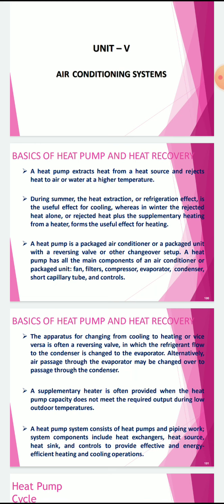A heat pump is a packaged air conditioner or a packaged unit with a reversing valve or other changeover setup. A heat pump has all the main components of an air conditioner or packaged unit like fan, filters, compressor, evaporator, condenser, short capillary tube, and controls.